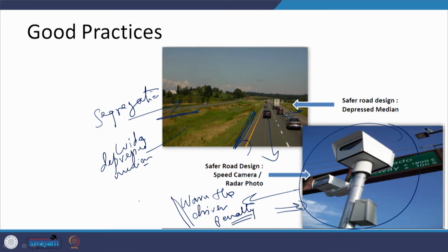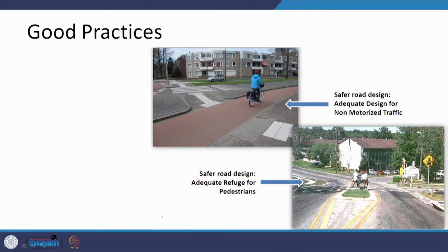So, this type of traffic sign needs to be provided, and we did discuss this type of sign where the panel provisions etcetera can be there. In such cases, the red color background can be utilized with white fonts on top of it. Here again there is a design where the cycle track is being provided. There is a texture being used, and this texture distinguishes it from the rest of the paths being provided for other users.